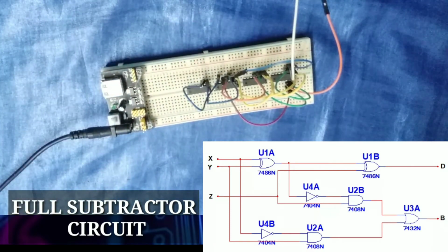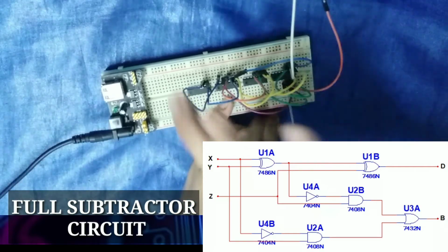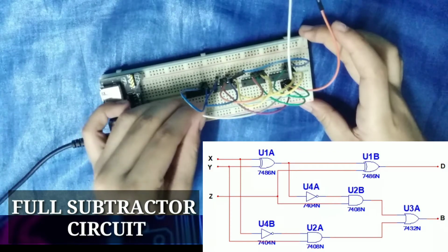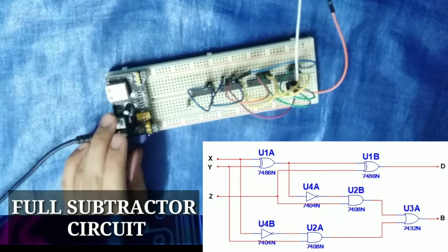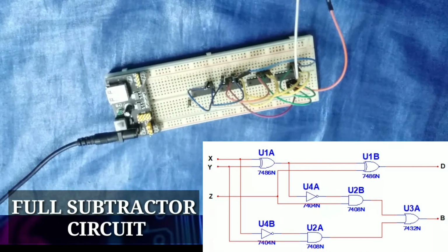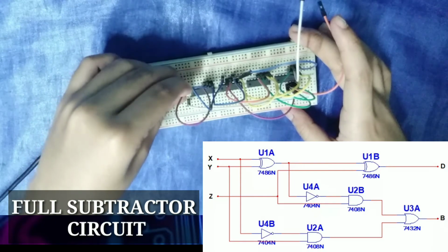Now, for our output connections for the two LEDs, we will be connecting our white wire here on the 11th pin of our 7486, and let's put it here. Okay, and do not forget our output for the 7432 integrated circuit. Let's put it on the 3rd pin of our 7432 IC. So let's put it here.